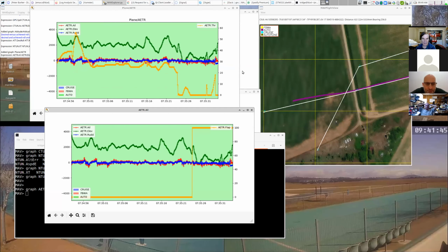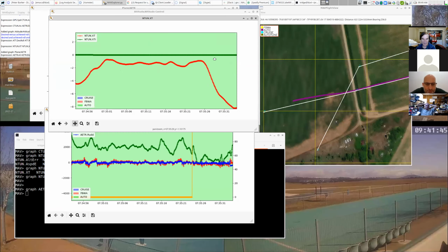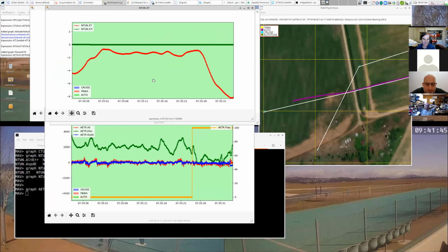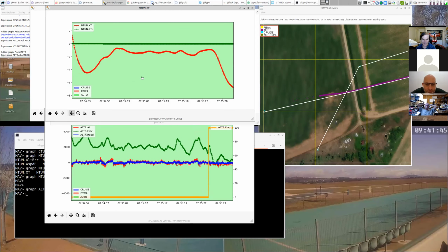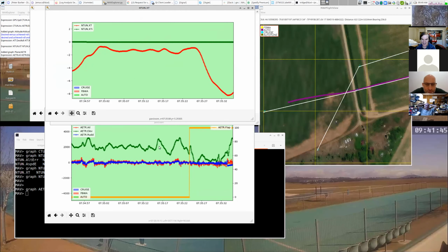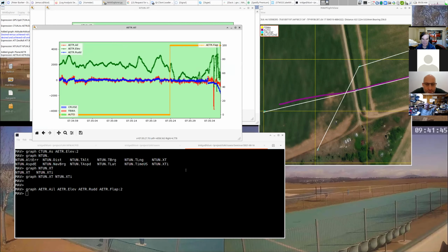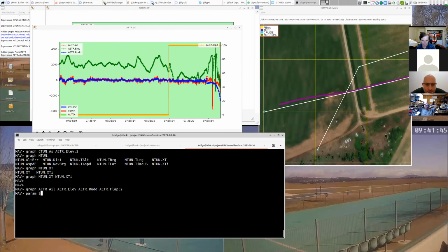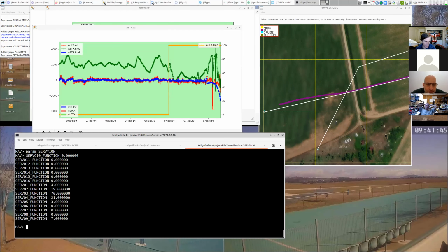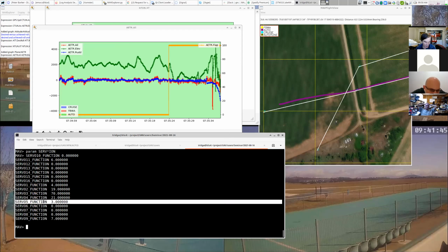And so what you'll see is that at the point where it suddenly needs more cross-track, that's the point where he shoves the flaps on, right? And as he shoves his flaps on, over the next couple of seconds, he suddenly needs more roll. Now let's make sure he's actually got flaps. Param Servo Star ION. This type of aircraft usually does have flaps, and we can see that Servo 5 is type 3, which is auto flaps.